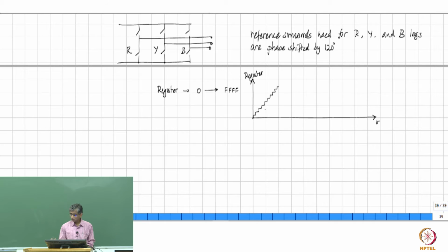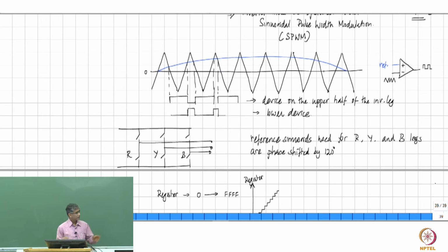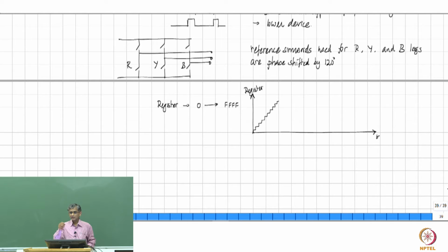And because of this, you can't have a high frequency waveform that is going to go negative, right. So in a digital implementation, that is exactly what you will do, that you will level shift the AC waveform by half this amplitude, and then do a comparison of the numerical value of the amplitude level shifted with this waveform that is also level shifted, right. So you still get the same sort of output in any case. So this would be the manner in which you would do it in a digital implementation.